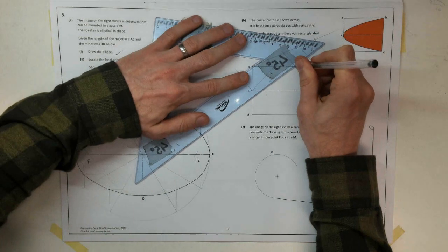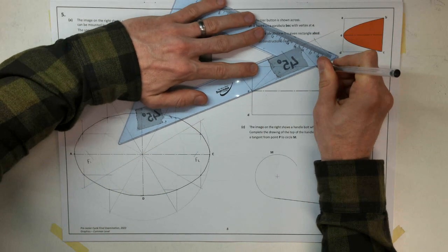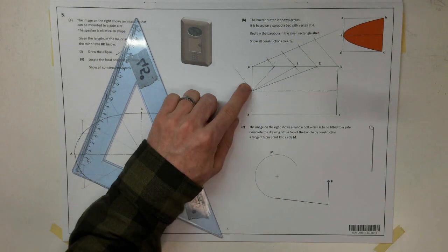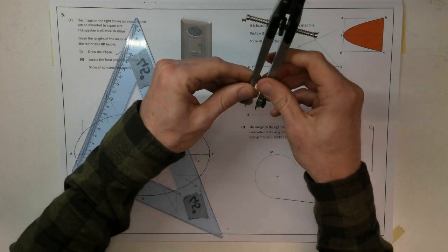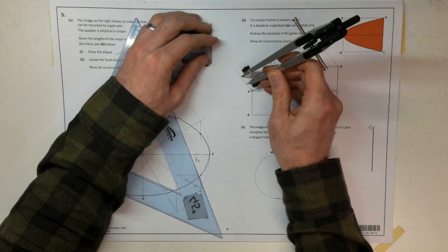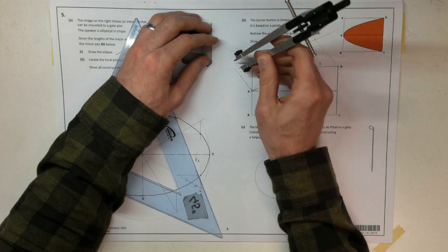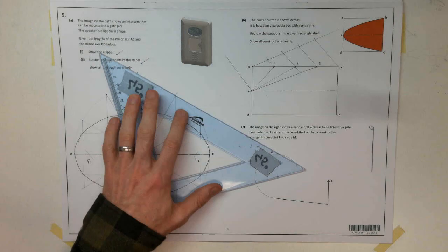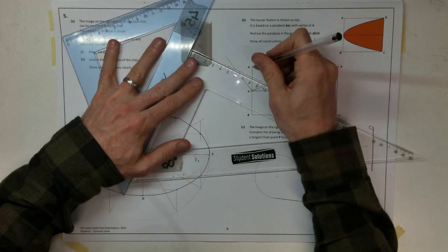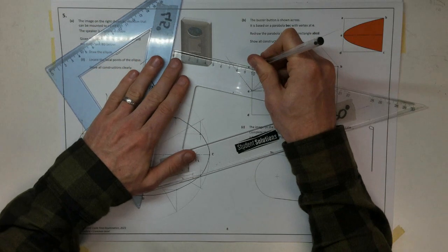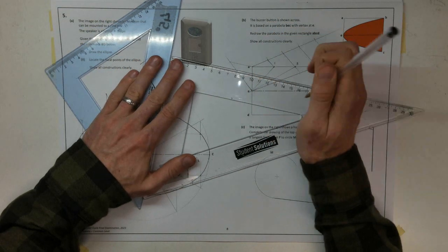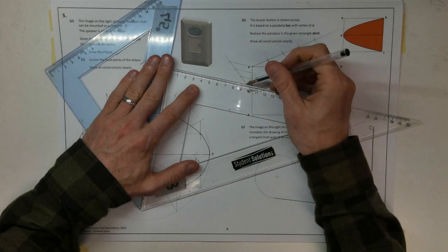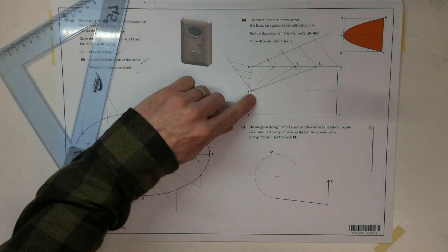A very common mistake is for people to draw those lines down the page. Now we want to divide up this side into equal parts, so let's go 1, 2, 3, 4. Extend that line on a little bit. I'm going to join the ends back to A. Yours might look slightly different if you've got a different angle or a different distance, but what's important is we're doing the method correctly and dividing a line into equal parts, and we get this here.